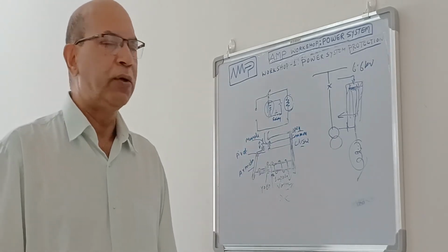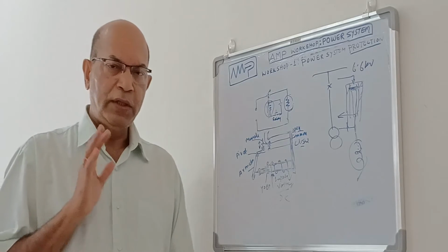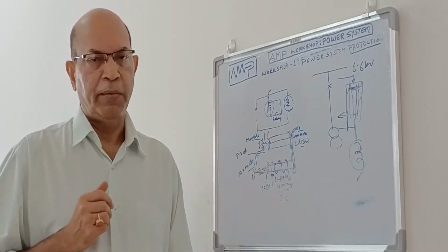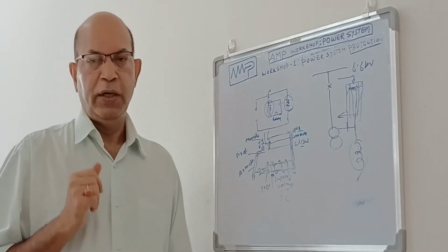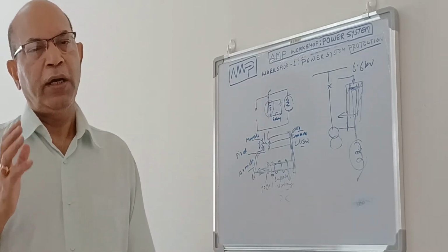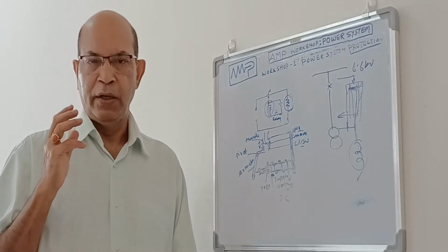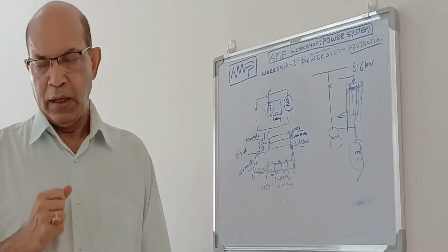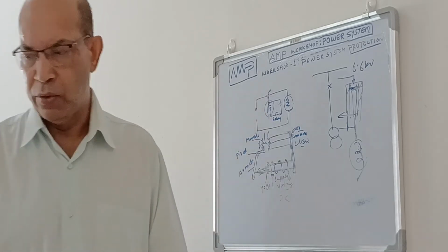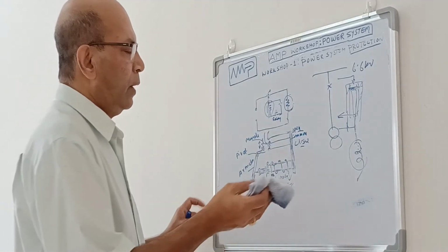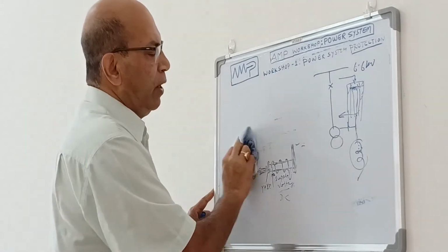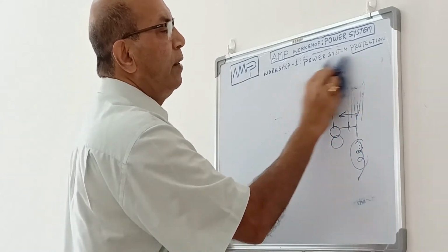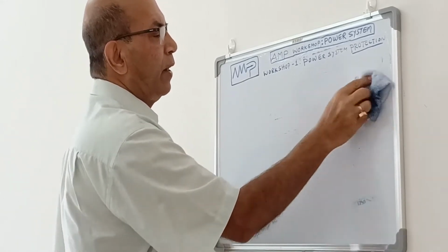Now the next point we will go to. This is the relay, so with the relay we will now go to the three different types of relay. First, the electromagnetic relay. The electromagnetic relay works on the principle of electromagnetic attractive force, or electromagnetic induction. In the case of electromagnetic attractive force, we know that when a coil or solenoid carries a current, either AC or DC, the solenoid gets magnetized.